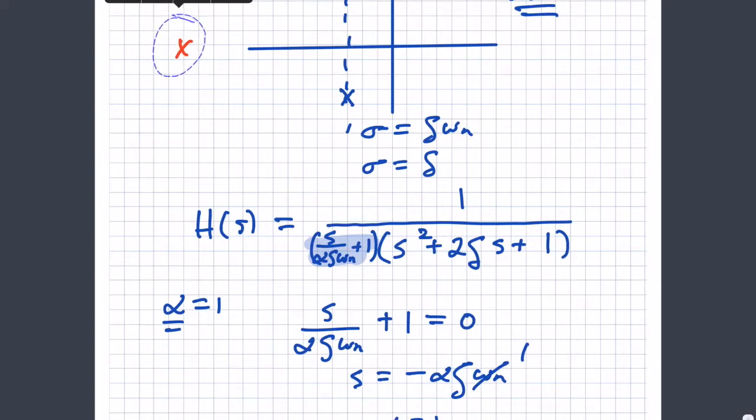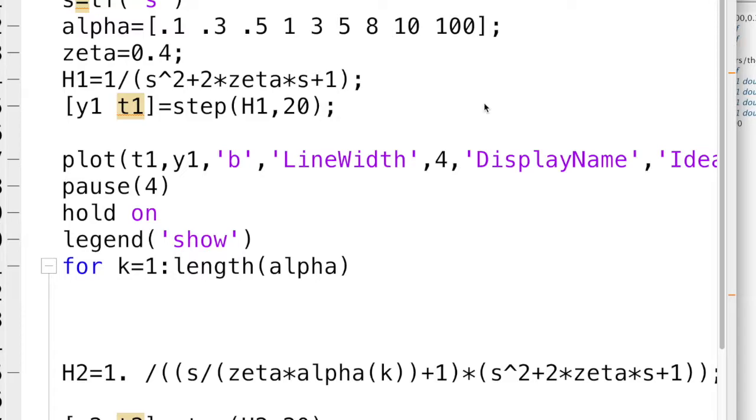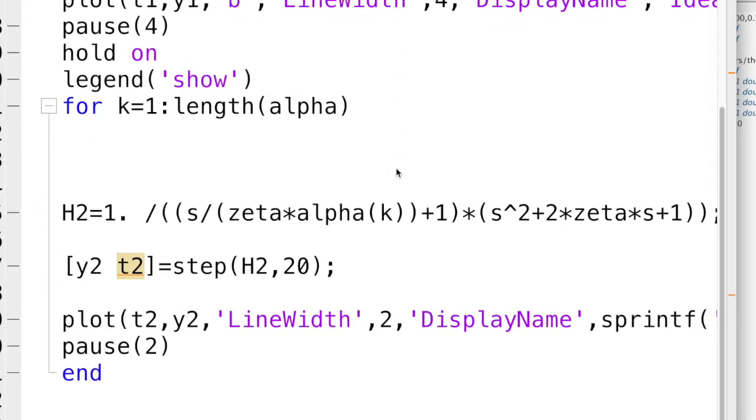All right, so that's the setup. I'm going to go to MATLAB next, and we're going to study the output response when we have a nearby real pole. This is a MATLAB script to plot the step response for the case where we have a second order dominant pair of poles. We say dominant, but it's not necessarily going to be dominant. But we're looking at what happens between the ideal second order response versus when we have a pole that gets nearby.